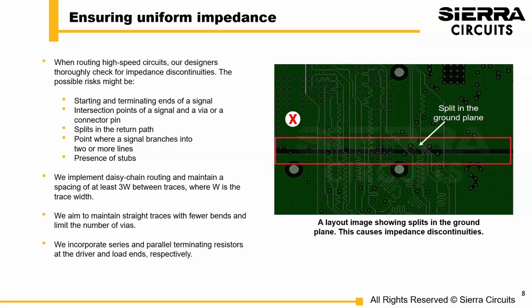We implement daisy chain routing and maintain a spacing of at least 3 Ws between traces, where W is of course the trace width. Additionally, our designers incorporate series and parallel terminating resistors at the driver and the load end respectively.